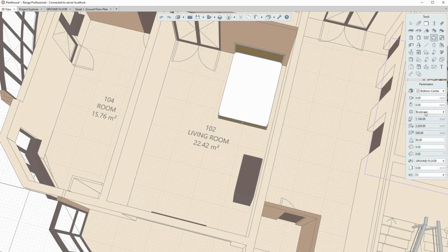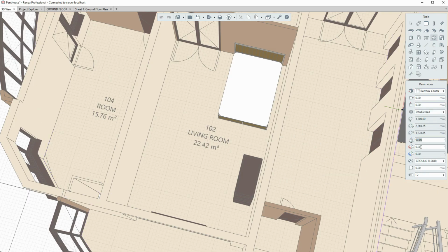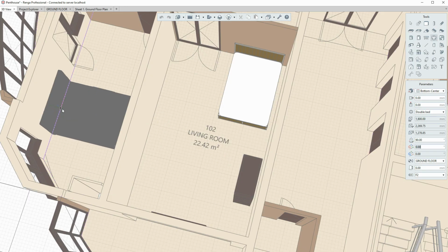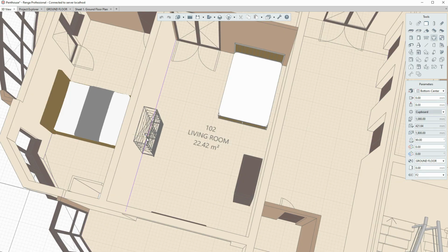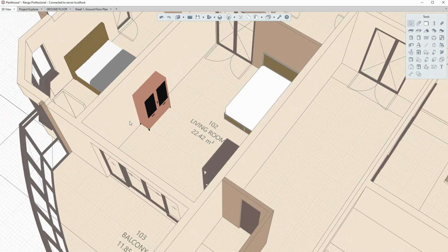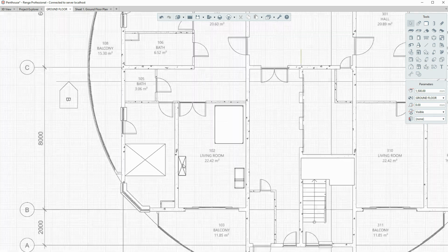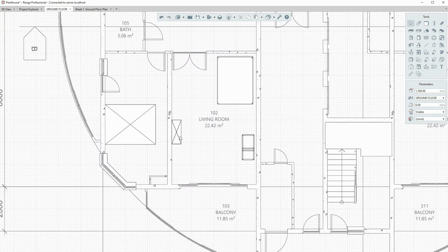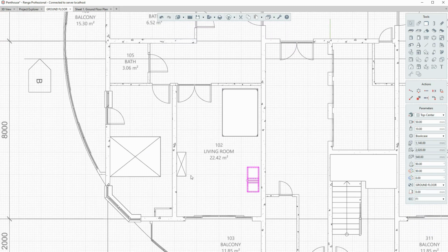The single bed and the bookcase elements are created from imported objects in STEP format. The double bed and the cupboard elements are created from imported objects in FBX format. For elements created from imported objects in 3ds Max, Lightwave, Stereolithography, OBJ, Collada, FBX and VRML formats, only the bounding box of the imported object is displayed on the plan level. Elements created from imported objects in C3D, STEP, IGES, Parasolid and ACIS formats are solid and their projections or sections are displayed on the plan level.